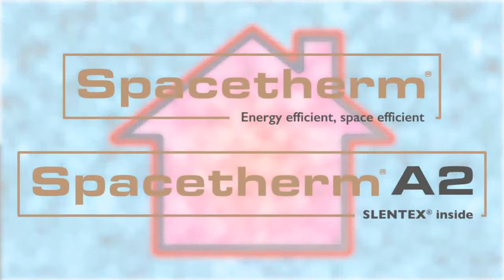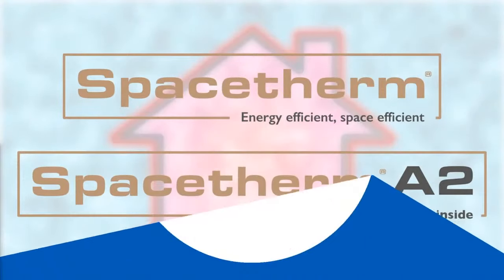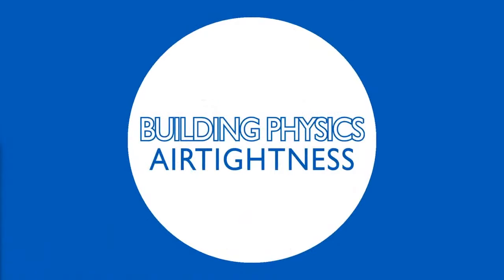Maintaining the continuity of insulation can pose challenges in some areas, such as window reveals, where space may be extremely limited. In these areas, thin insulation systems like our Spacetherm aerogel boards can help ensure this continuity without sacrificing thermal performance. The other way we can optimise our energy performance is by paying careful attention to the airtightness of the building. By this we don't mean sealing up the inside entirely, but simply ensuring that the only air movement is air movement we can control via ventilation systems.